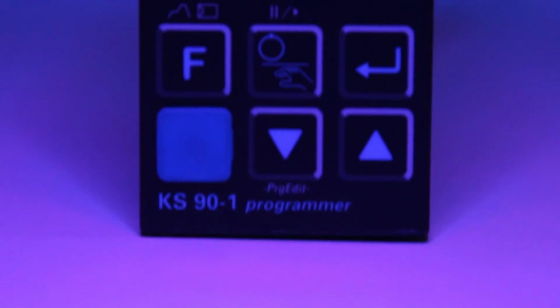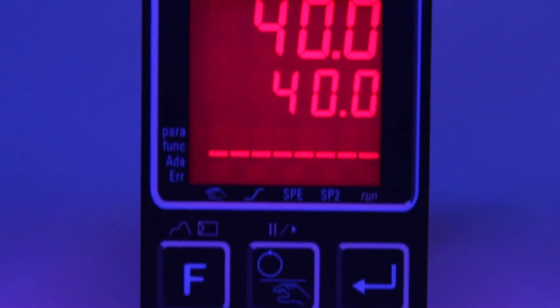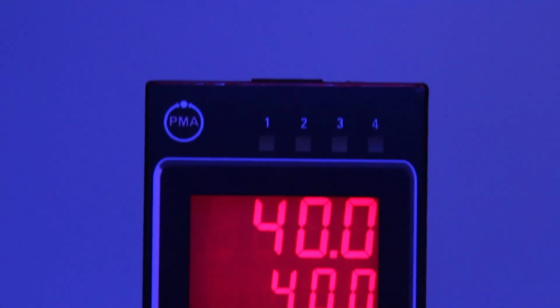You may think that there's a heavy price premium to pay to get the benefits of PID control over proportional or on-off control. This is not the case. Virtually every controller from West is capable of full PID control as standard. The integral and derivative functions can be turned off if not required, and it's even possible to set the controller into on-off control mode if that is what you need.